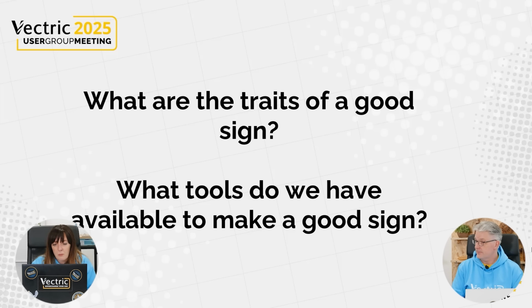Now, sheriff stars, at least the little sheriff's badges that I've seen, always have those little balls around the outside edges. We'll go into our circle tool, and I'm going to create a circle with a diameter of 1/4 inch, 0.25. And I'm just going to click on the points here, and that should snap on there. Oh, that might be a little bit small. So let's change that to 1/2 inch then. And we'll apply that. Oh, that's better. So now we can just go ahead and drop those on there where they belong. Close that down. And I think that looks pretty good. That's awesome. Great.